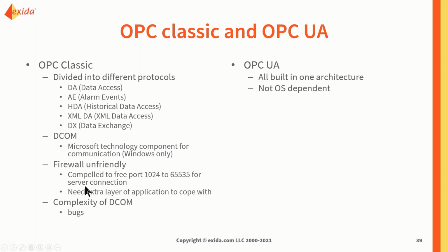Another problem with OPC Classic is that it has a big problem with firewalls. It's very firewall unfriendly, because in order for the OPC connection to work, you need to put a big hole in the firewall.